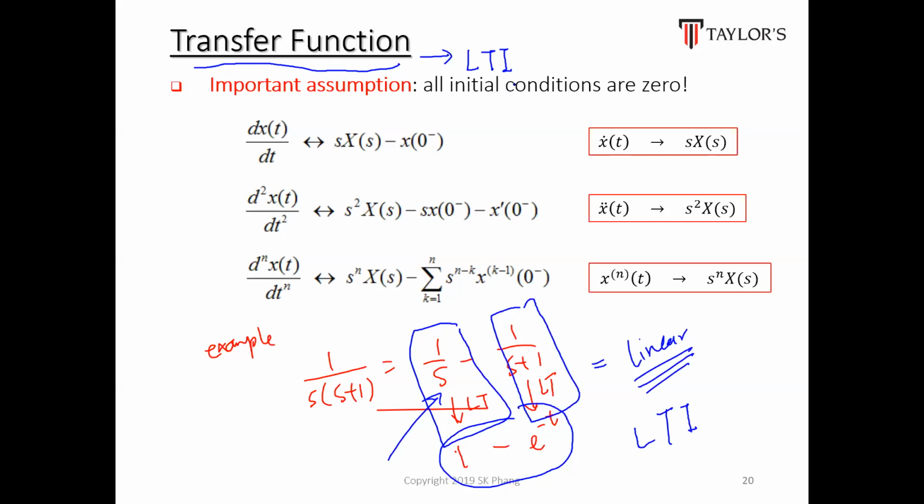Sir, if that is the case, can the Laplace transform work on other systems as well, like time varying systems? Let me think. For non-linear systems it definitely cannot. For time varying systems I need to check, but my suspicion is that it cannot, because in a time varying system, applying the input at one time is different from applying it at another time.